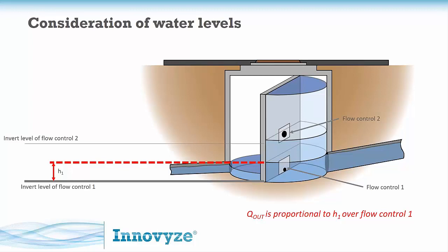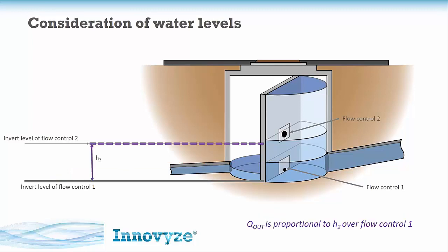If we look at a secondary water level though in the design, what we have to consider is that any second head, irrespective whether it was our design head or not, it's going to change the amount of flow through the flow control. And this is the point that Chris was making earlier about the fact that we may actually be able to hit multiple different discharge considerations using a single flow control. So I'll show you how we have to consider that and why we need to be careful about that as we go through the design of our complex flow control in a second. But just to show you, subject to a different head, we get a different flow. We're only using one flow control that's active at the minute.